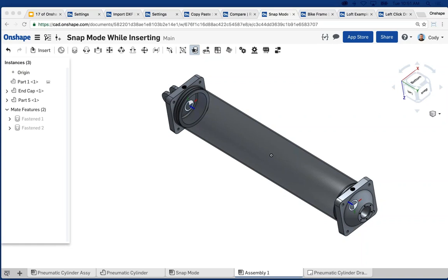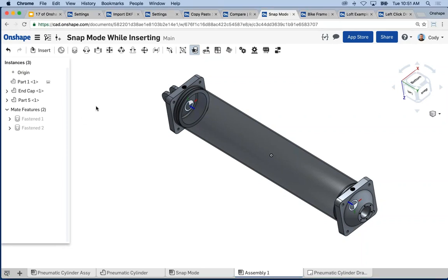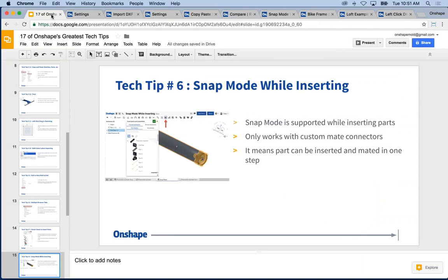I don't have any specific examples, and again, that's a little more specific than I wanted to get into with this webinar. What are the caveats for importing supported drawing formats that could actually be editable in Onshape? DXF and DWG are the two formats that we support. We have some limited editing capabilities, and you can drop it into a sketch and extrude it or evolve it, or turn it into a 3D model. I'll show you an example of that in just a second.